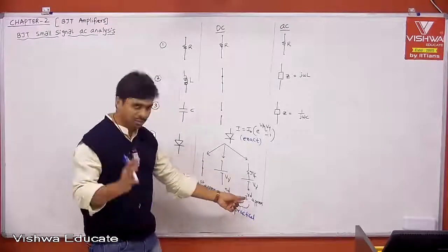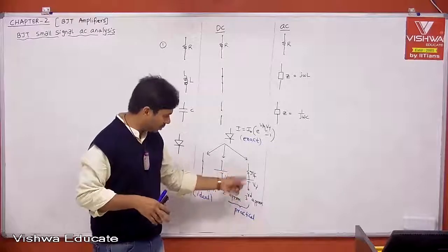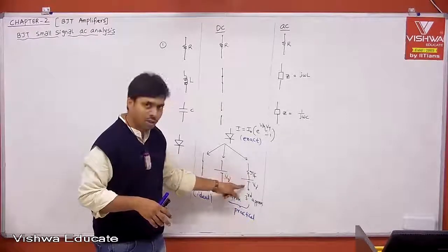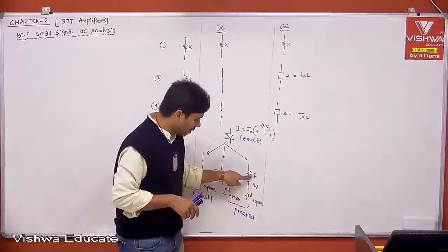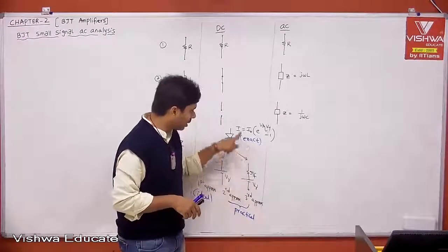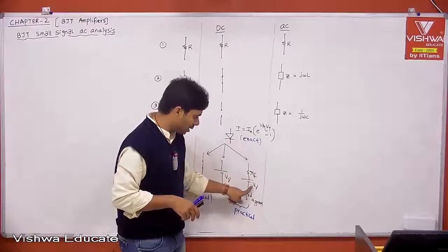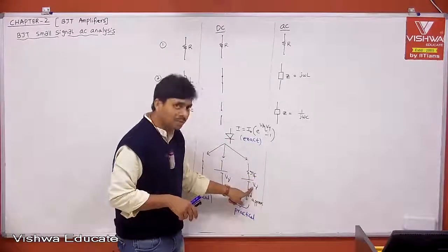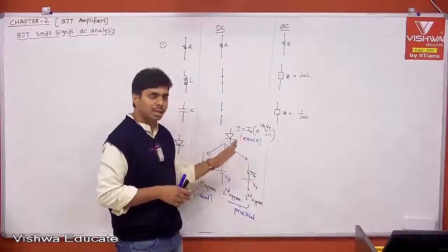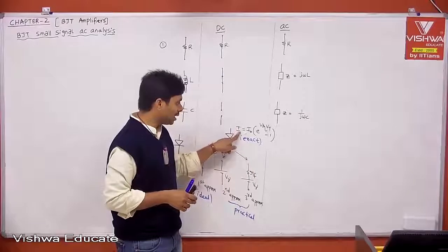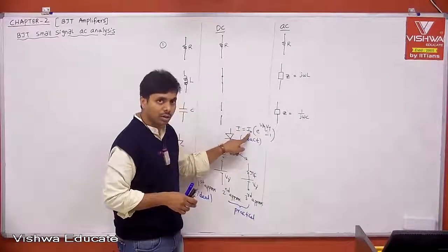Maybe if you take the third approximation, that's why earlier I was trying to take this, because I have a resistor as well as a voltage source, right? Therefore now, this is already the dynamic resistance which you already calculated from the exact equation. Then how will you calculate this V gamma? Sometimes people will ask you to use the exact model only, even though this is DC analysis, because this is capital I and this is capital I naught.